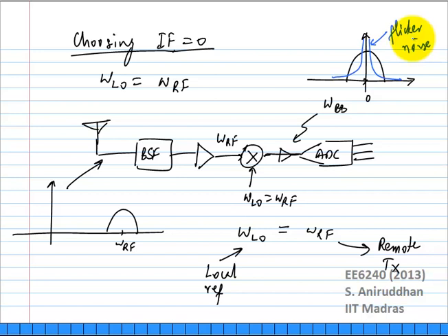Yeah. This is the flicker noise after the mixer, not before. Before you don't care. It is flicker noise after, that's why I said ADC or any amplifier you have after that. Okay? How do you take care of this problem? Do some chopping. I thought a mixer is what chopping is, right?